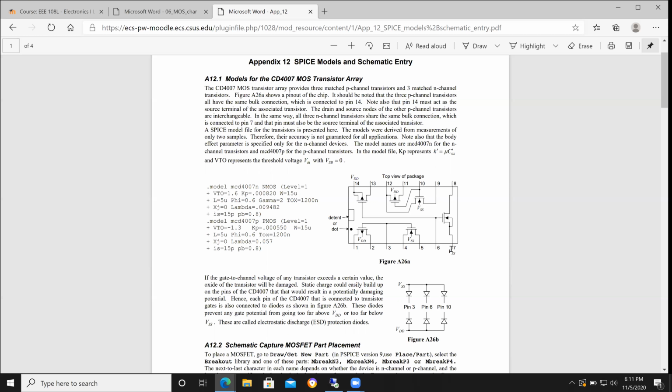So you could manipulate the threshold voltage by changing the body voltage, and that's something you'll see in this lab. You can either make it a larger threshold voltage, which might be advantageous for an application where you want really low leakage current, or maybe you need a device that switches really fast, so you lower the threshold voltage.